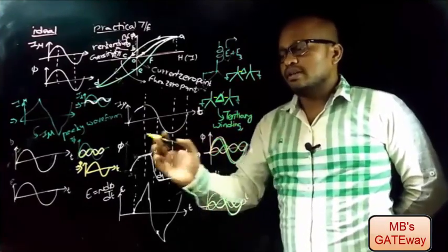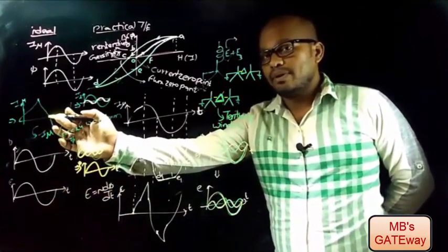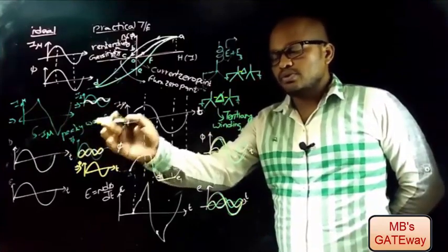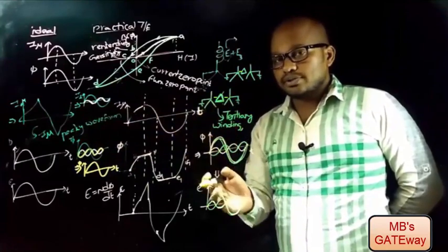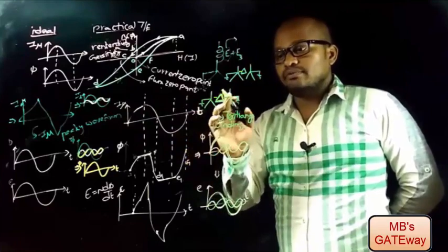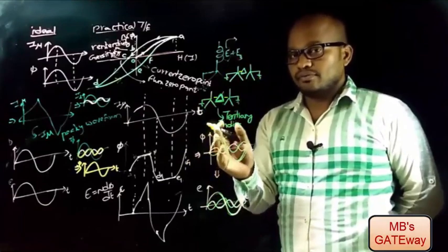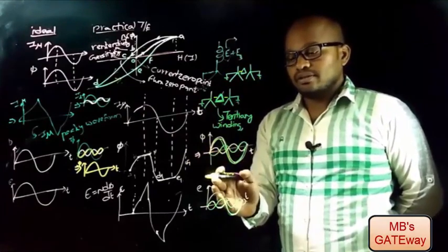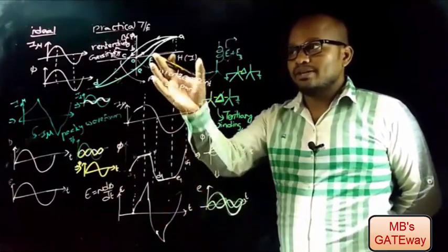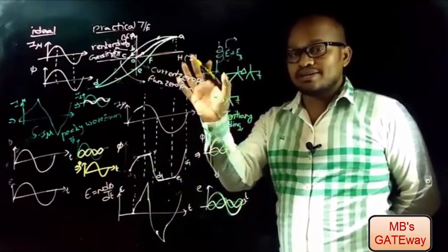Therefore the conclusion here is that actually to get sinusoidal output EMF we need to give a peaky waveform as input to the transformer, and this peaky waveform is very difficult to obtain, so we need to think of how to get sinusoidal output with sinusoidal input, and for that we are providing a path to the third order harmonic, because of which we get sinusoidal flux set up in the core, and that will cause the sinusoidal output EMF. And to explain this concept we make use of this BH curve. So this is the importance of using the BH curve in transformers.